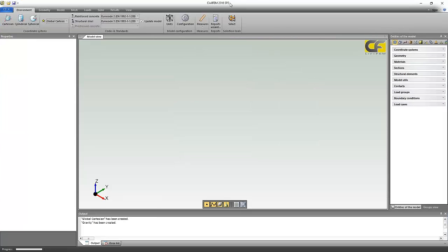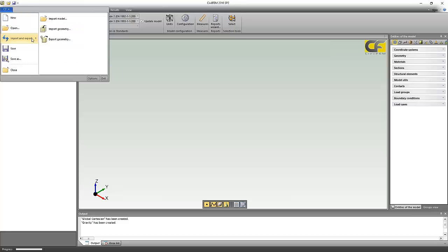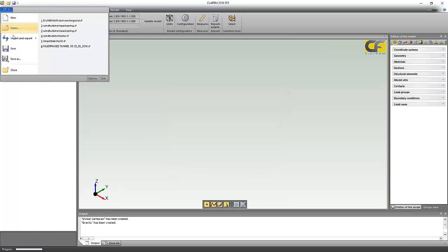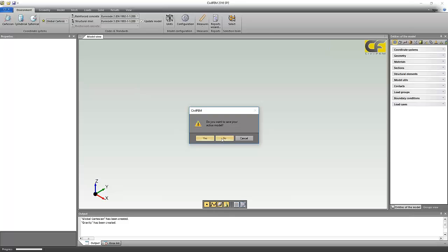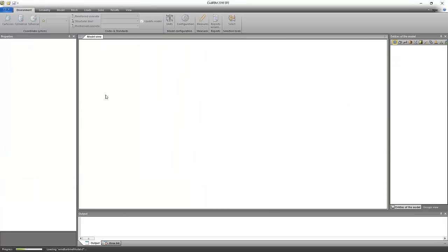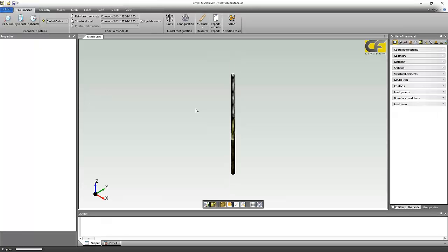In case you have already done a structural analysis, you can always import your model and start from your geometry, mesh and loads, and then start with a modal analysis or transient analysis or whatever. So yes, you can modify the analysis type and then import the model. So in one model you can solve all these types of analysis.